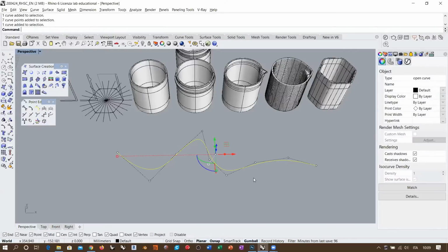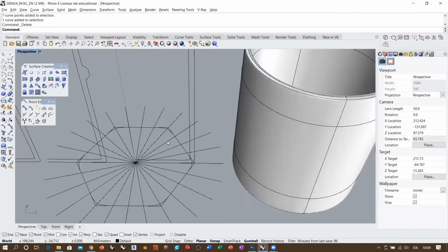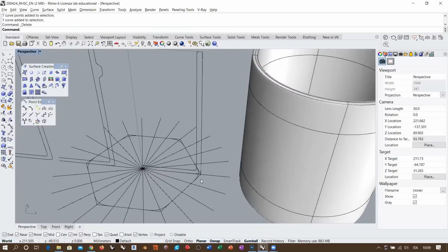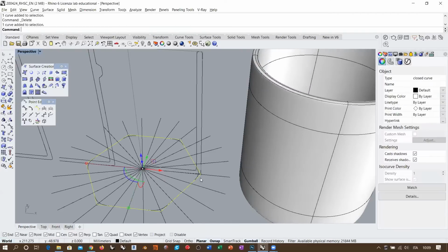So it's impossible that you get this kind of strange internal behavior for a NURBS curve or a NURBS surface that you create with any command in direct surface modeling, unless you create it with a particular set of construction curves. For example, if you create a revolve with a hexagonal polyline, then you will have kinks on the sides, on the vertices of the hexagon.